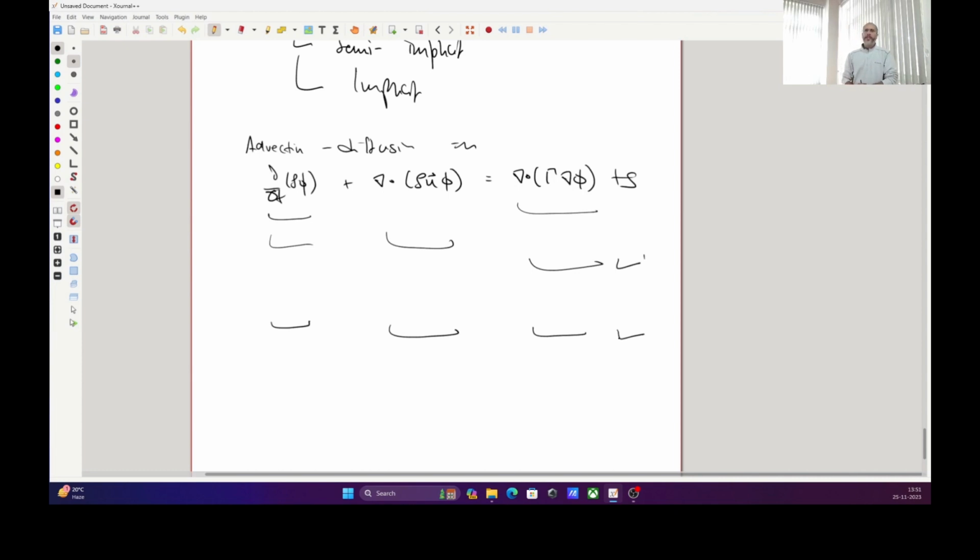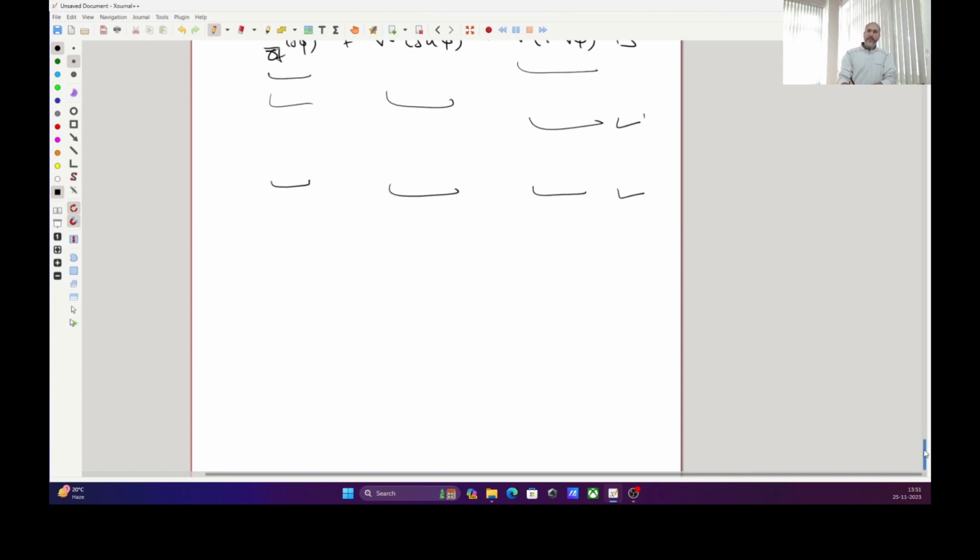But you may have situations where you are dealing with transport of, let's say, concentration, or convection in heat convection. So there you will have these terms where phi will not be velocity. That's a bit easier to solve, right? Because u is already available to you. You simply have to implement the terms. But there what happens is that now you have both convection and diffusion terms. So you have to figure out how to discretize them.